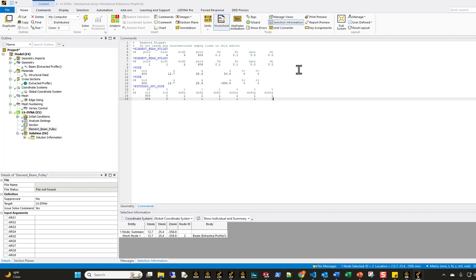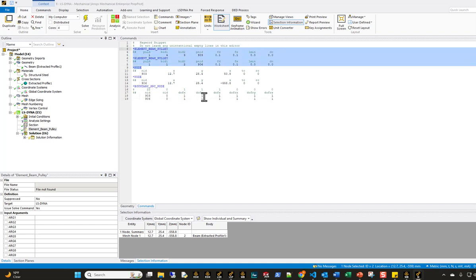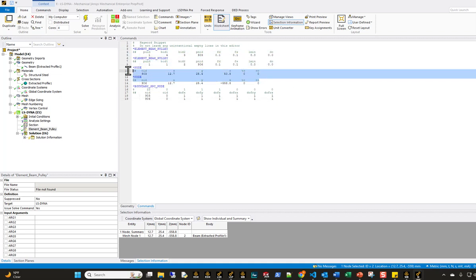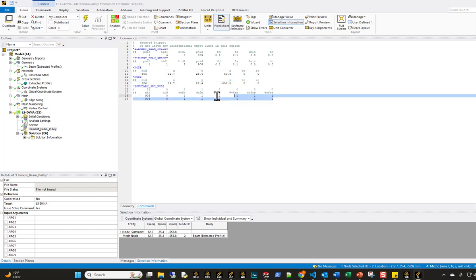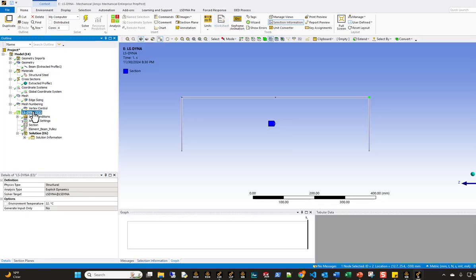So quick review. We created our element Pulley. We reference the node we just created in here as a Pulley node, which is coincident with the location of the node shared by the two truss elements, right, beam elements. And then lastly, we're going to lock the 903 and 906 nodes down because those are Pulley nodes which cannot move. And that completes the definition of the element being Pulley, right?